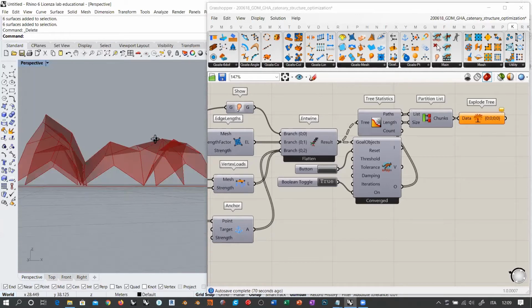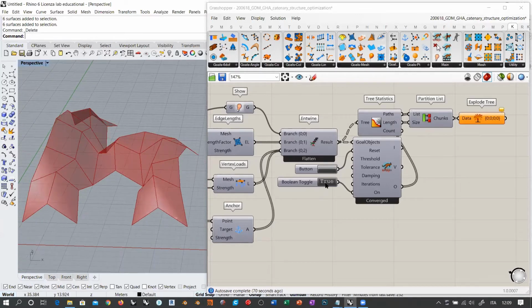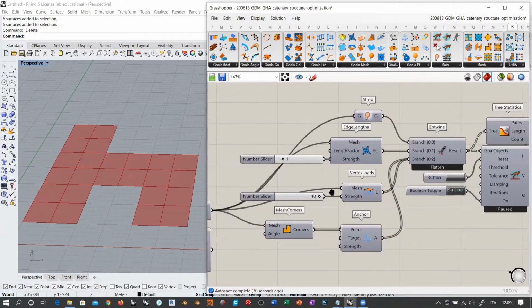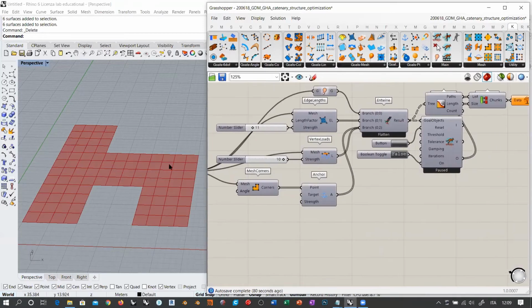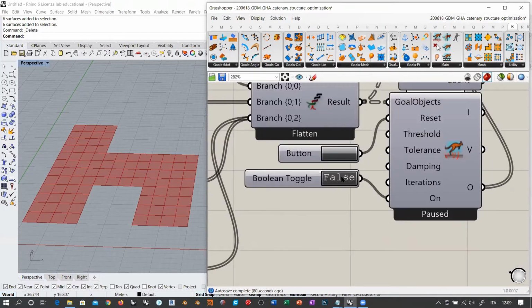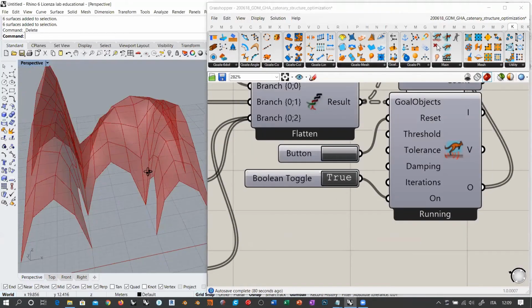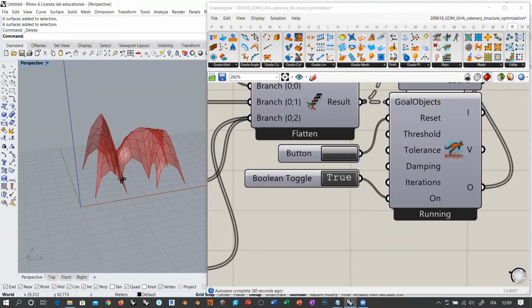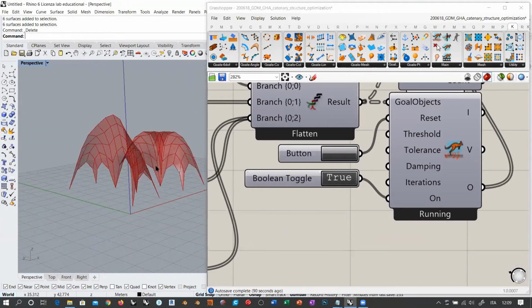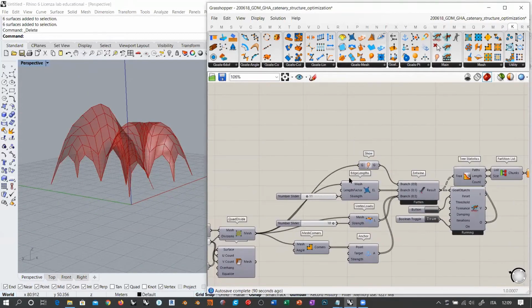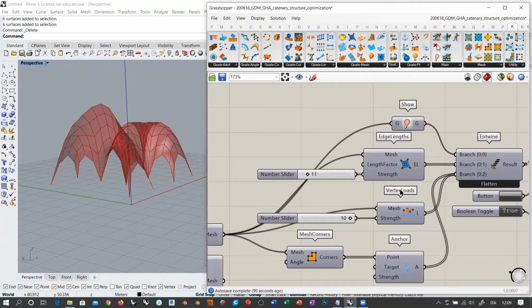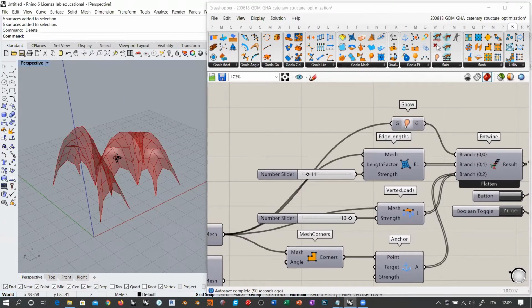Okay, as we are going to work with Millipede, what I suggest in this phase is that we take the original system and increase the amount of subdivisions to 4x4 at least. So we have a more catenary style behavior. This deformation here is something that depends on the elasticity of our system. So this is just visual.